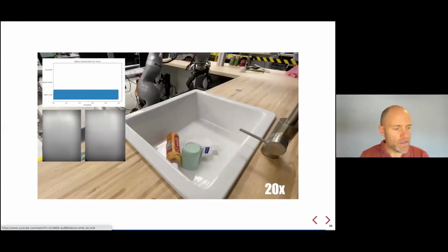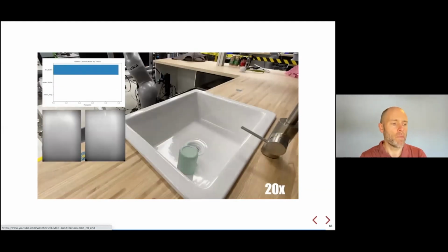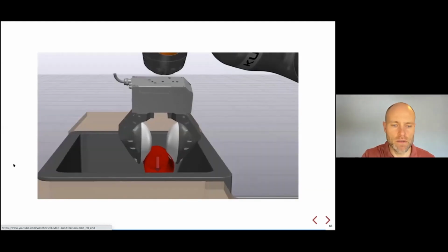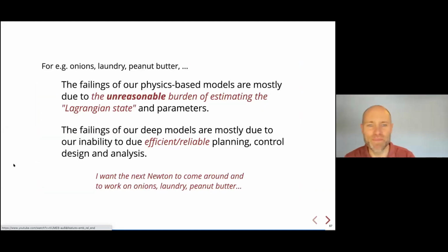So I don't worry about the dimensionality of the data. And you're right, it's super good. I'll maybe stop playing that just so people can listen. But I think the problem with head-mounted cameras is as soon as you put your hand down in front of the object and things are about to get interesting, you've occluded your head-mounted cameras. And okay, I'll put a camera in my palm. But then the minimum range of the sensor becomes the problem. And really, it is the case that our camera-based sensing sort of dies out right at the part where the manipulation gets interesting. So tactile, I think, has a huge role to play.